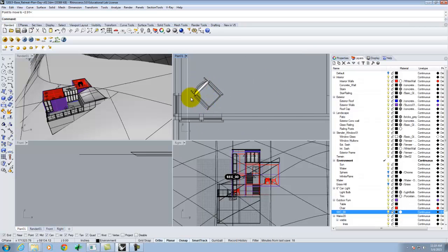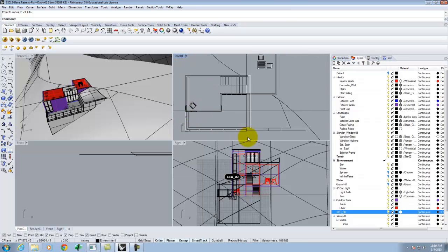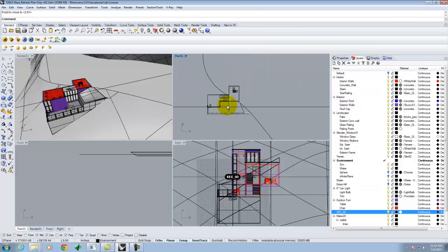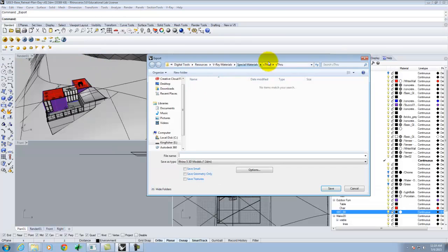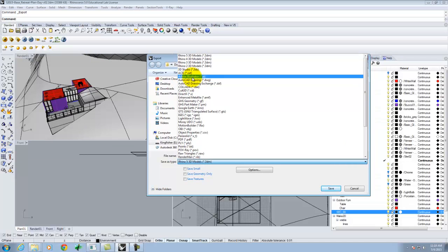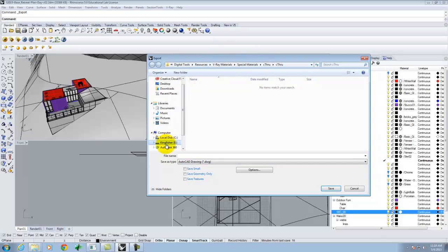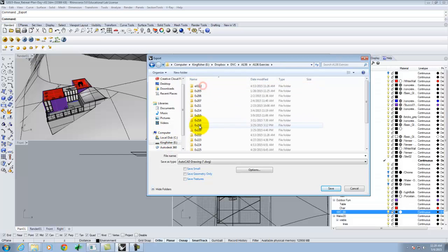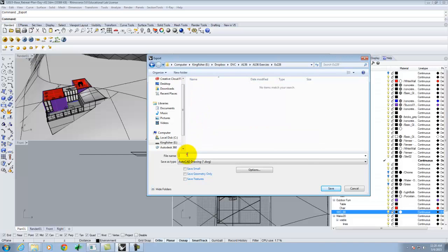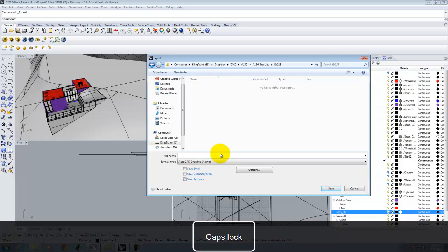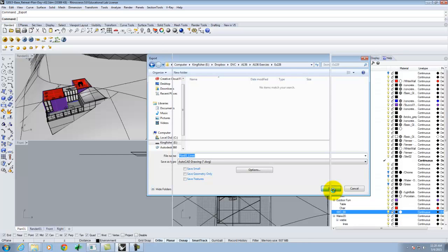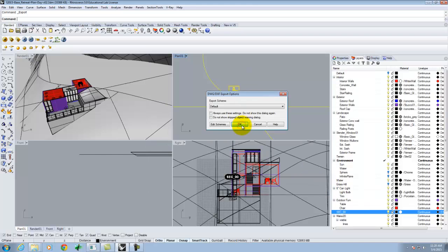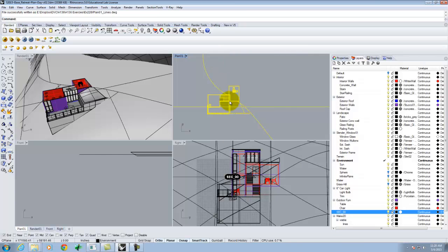And notice that it does include my chairs, right? All of my windows, right? And the hidden lines are that whitish color. Okay? I can go ahead and select these, and I can go to File, Export Selected. And just like we've done before, I could save this as an AutoCAD file. And let me save it into my flash drive. Hold on a second. This is 228. And I'll go ahead and click Save. And I'll say OK. So that gives me the basic line drawing that represents this sectional cut.